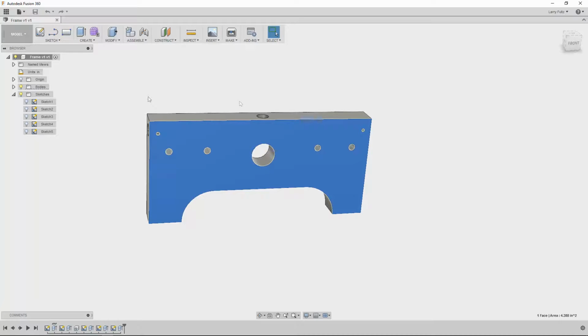So we're going to break down each one of these sketch elements here. We're going to make them a little bit simpler, as well as get rid of some of the redundant geometry, as well as some of the orphan geometry, and make sure that everything's fully constrained. You'll see the reason for creating defined geometry immediately in the first sketch here. So let's go ahead and jump right in.